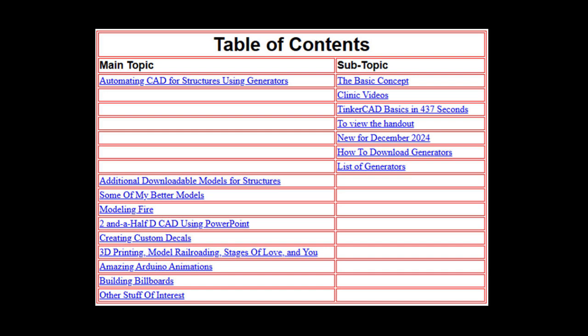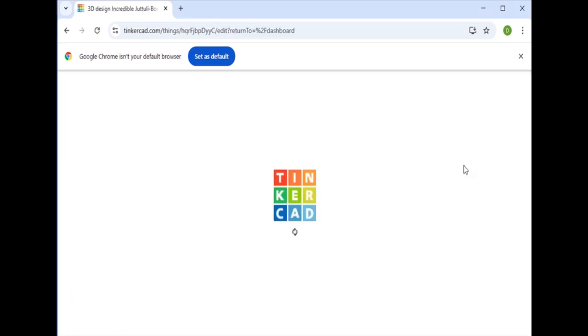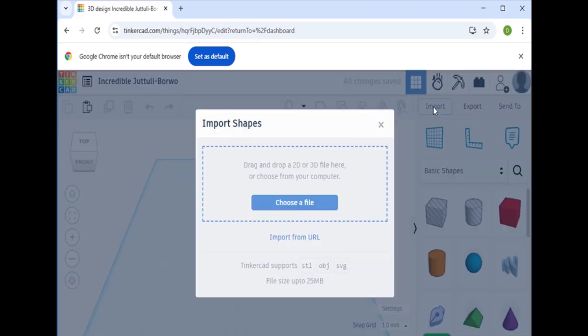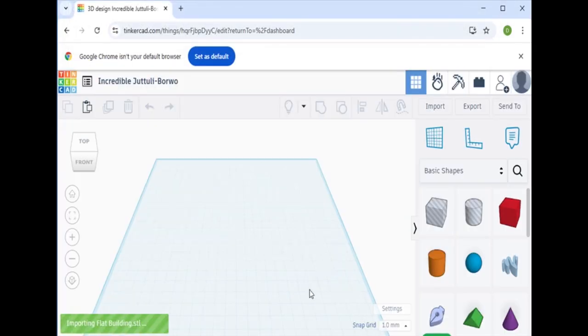Finally, there is this thing about spending 8 minutes, it's actually 7 minutes and 17 seconds, learning computer-aided design. The basic building has no holes for windows or doors, but there is another free software tool called TinkerCAD which allows you to punch holes into a basic building. All you do is import your STL file created in the OpenSCAD step, grab a hole tool from the TinkerCAD toolbox, drag it to where you want it in the design, and group the hole with the building.